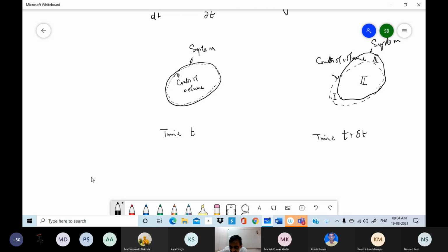If I consider a control volume, it's not very clear how to apply it, because apart from energy Q being supplied and energy W being expended by the system, I also have energy being carried along with the mass which is crossing the boundary of the control volume. The boundary of the control volume, there's a shorter name for it, control surface.